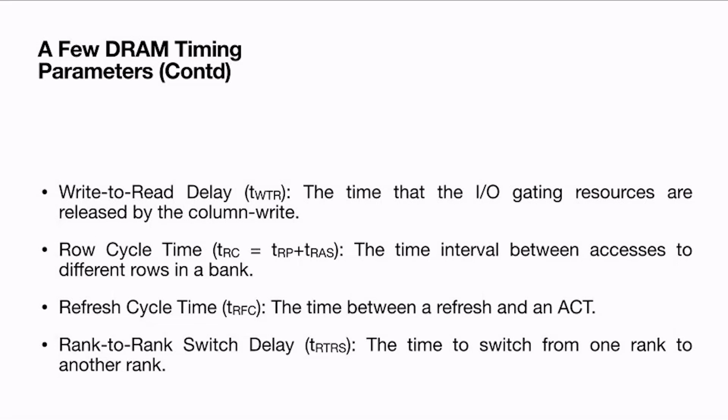And that is the sum of the times you have to wait for performing an operation from a different row, or activating a different row in the same bank. And a refresh, as I mentioned previously, we regularly have to refresh. And once we issue a refresh command, the next ACT command can be given only after waiting for TRFC amount of time.